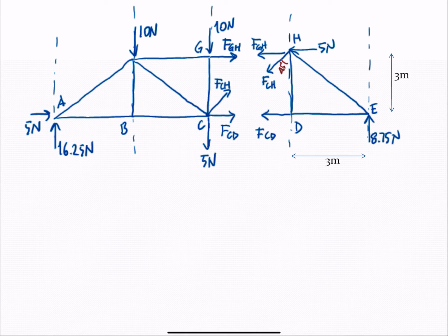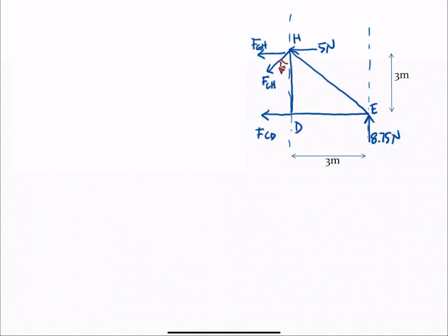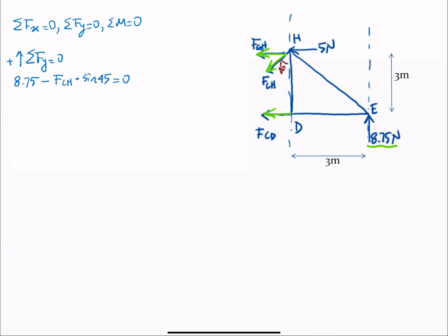The moment has arrived and we have to choose a half. So let's say we choose the smallest half, and we have 3 unknowns and 3 equations of equilibrium. So we apply our equations: sum of force in y equal to 0. I see an 8.5 force over here, so 8.5 positive.